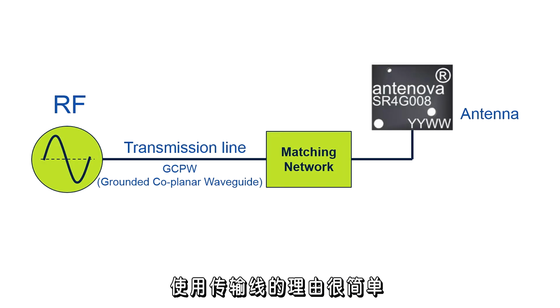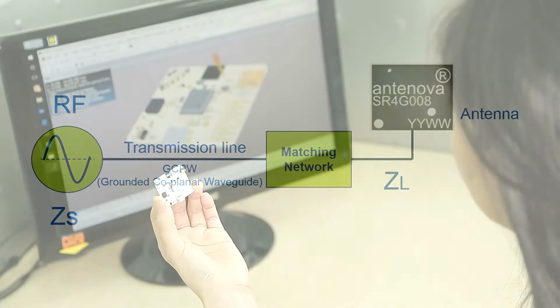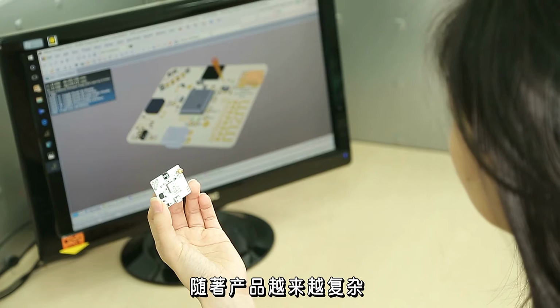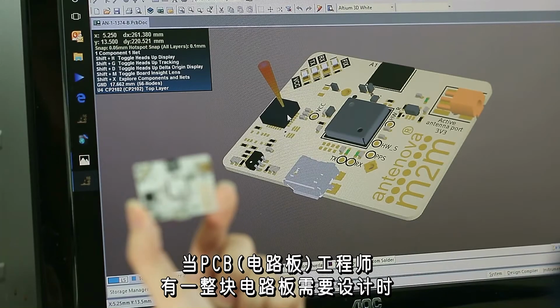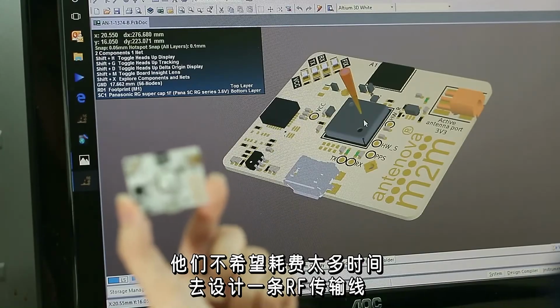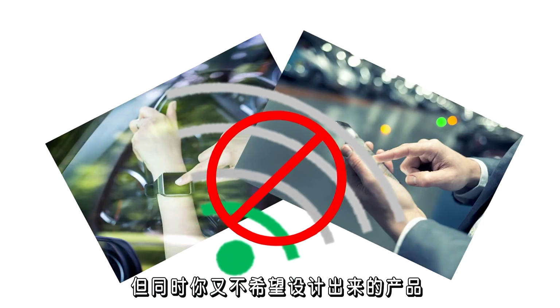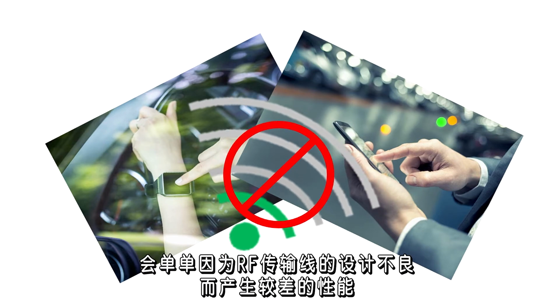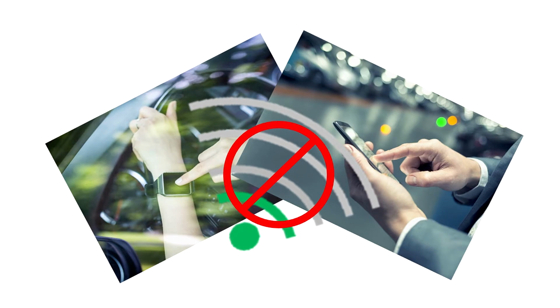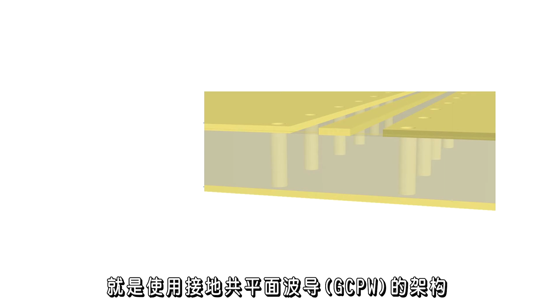The simple reason for a transmission line is to transfer RF energy from one place to another with minimal loss. With devices becoming more complex, PCB designers don't want to consume too much time on a single RF trace when they have the whole board to complete. But at the same time, the last problem you need is a device with poor RF performance because of that single RF trace. For embedded antennas, the most suitable antenna feed is to use a grounded coplanar waveguide.